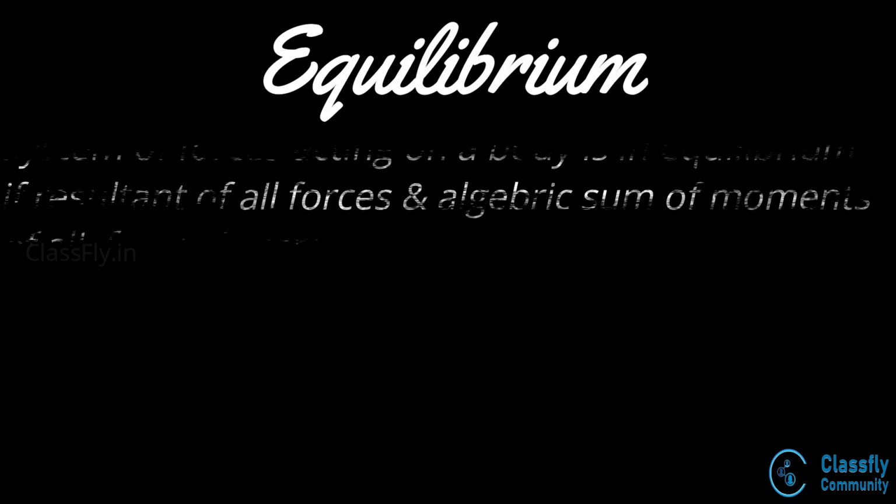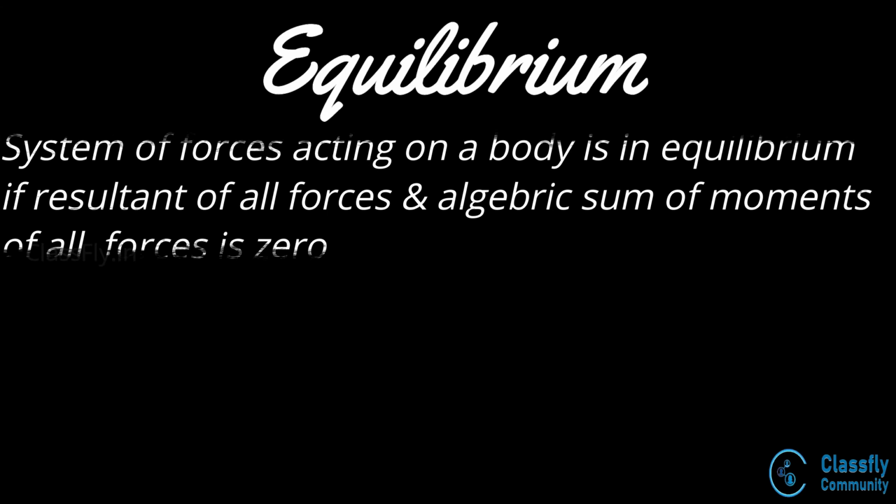Well, what is equilibrium? A system of forces acting on a body is said to be in equilibrium when the resultant of all the forces is zero and also the algebraic sum of all the moments of the forces is zero. Hence, when an object is in equilibrium, all the forces and moments are balanced and the net resultant will be zero, which implies that the system of forces or moments applied on the body will not bring about any change in the state of motion of the body.